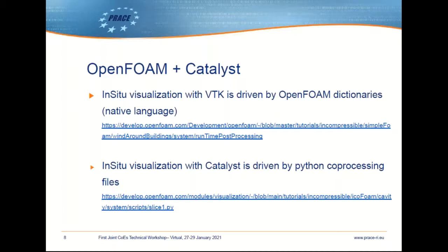If you're using Catalyst, the visualization is driven by Python files that are constructed using the ParaView GUI. So you have a Python script where you call the Python API of ParaView. It is required from a user perspective to know how to pilot an OpenFOAM simulation and how to pilot a visualization using Python VTK.